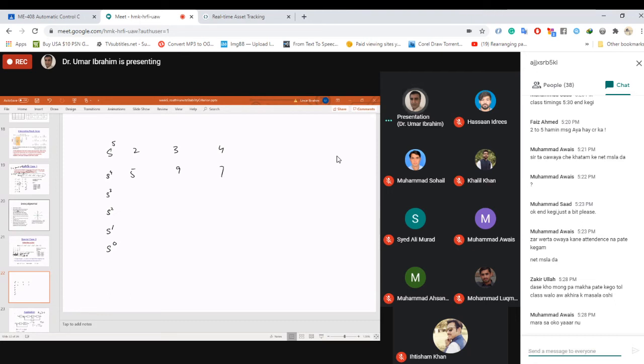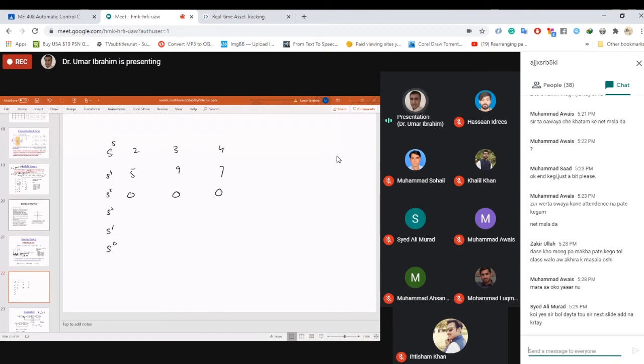Let's suppose this whole row comes out to be 0, 0, 0. Okay? Imagine when I calculate all these values as per the Routh stability table calculation, this whole row of S cube comes out to be 0, 0, 0. If it comes out to be 0, you cannot write epsilon here and keep these two values as 0, 0. That will be wrong.